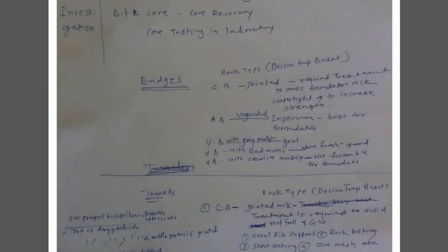Tunnel number 26 is excavated in flow number 212. Numbers are given to the flows, and flow number 212 is the one through which tunnel number 26 is excavated. Towards the Pune portal, that tunnel passes through amygdaloidal basalt, the top portion of this compact basalt flow, and lining is not provided there.